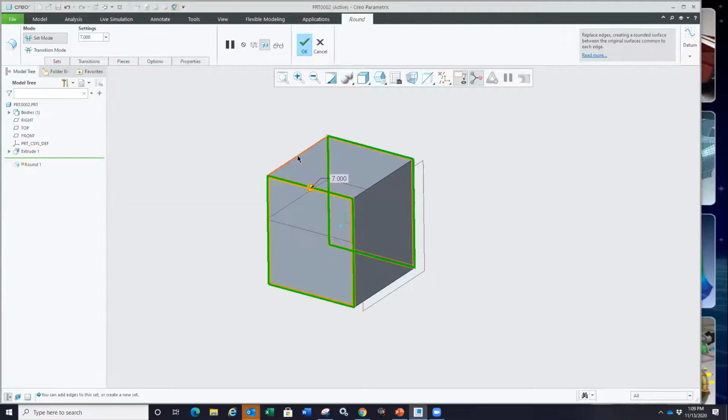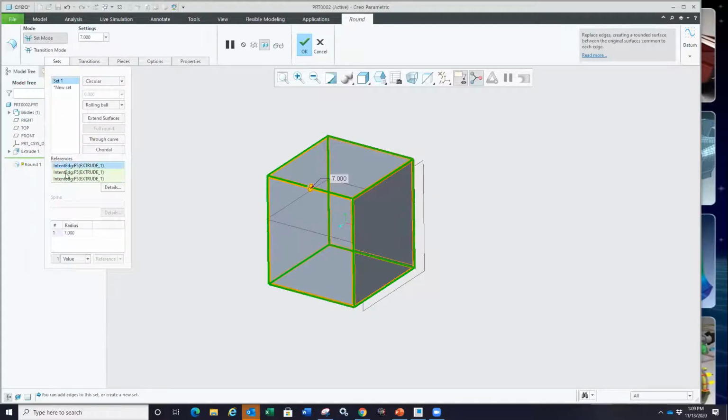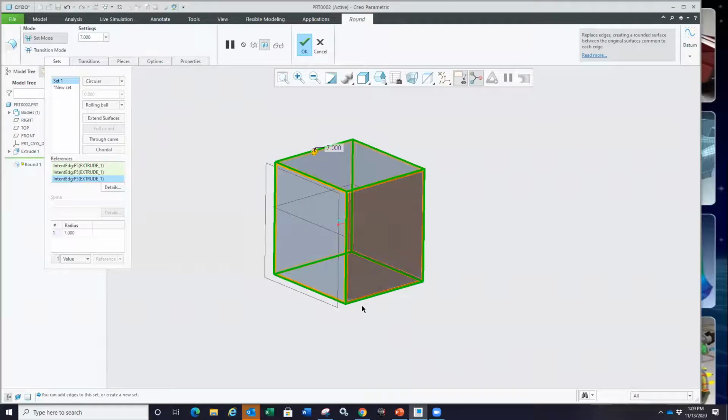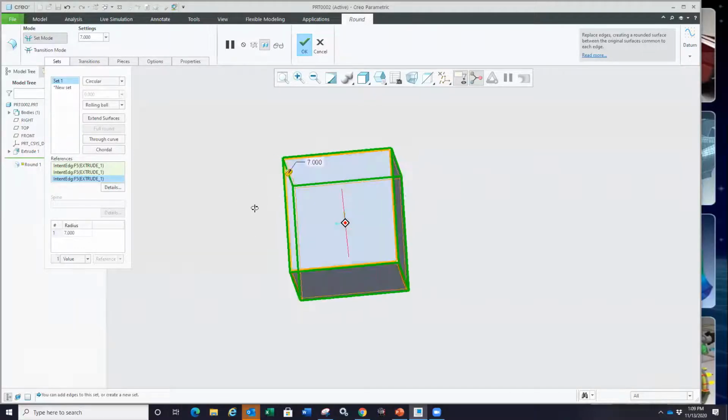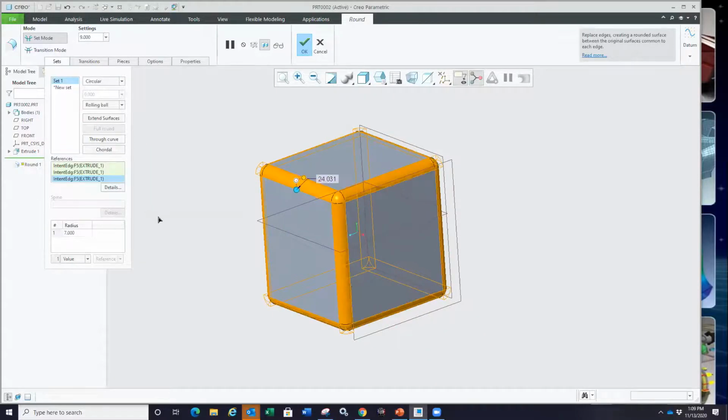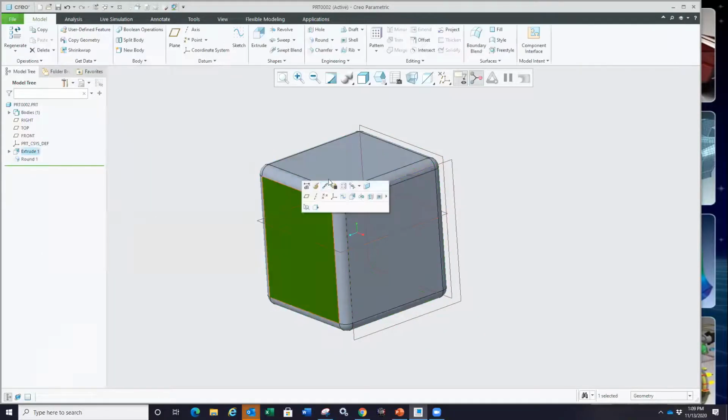That's an intent chain. So I got three intent chains, as you can see here, right? That's the rule. The rule is it picks up the shape that you sketched, the profile, and then the extruded edges. So when you make changes to these, for example, I've done this in here, and I'll just give it some value there. But when I go back to my